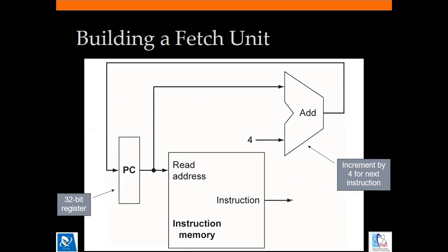And that will be used by the next hardware component in our processor. Along with that, the value of PC is going to be incremented by 4, as we have seen in the previous slide. Whatever output is generated would be written back to the program counter. And please don't consider this a write back operation. This is not a write back operation. So this is the fetch unit. I hope this is clear to all of you. If you have any questions, you can ask me.